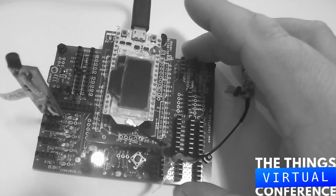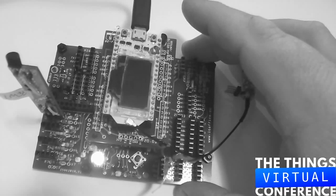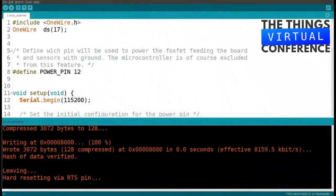And what do we do now? Can we see anything? Yes, we can, because in the Arduino IDE we can go on Tools, go down, pushing the menu Tools, going down on Serial Monitor and click there. You could also, instead of using the mouse, hold down, on Linux at least, Control Shift and push M. It would be the same.